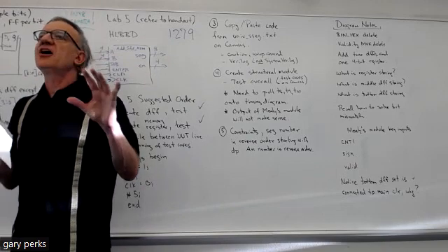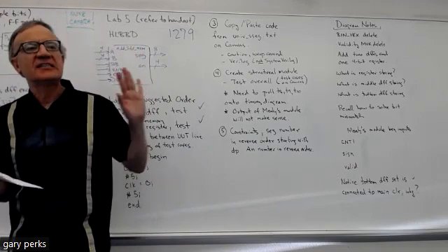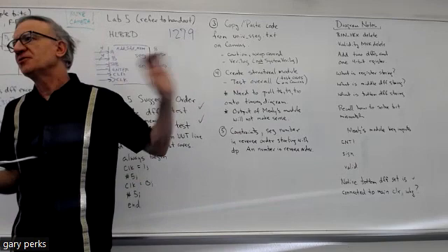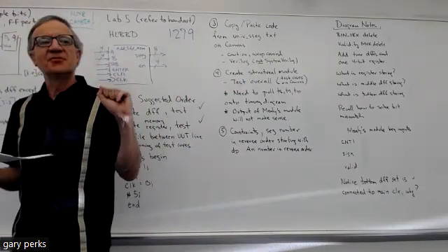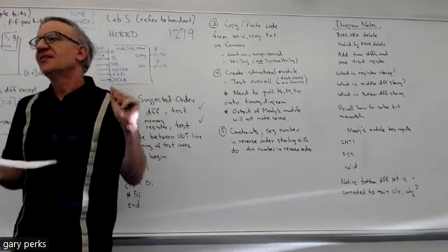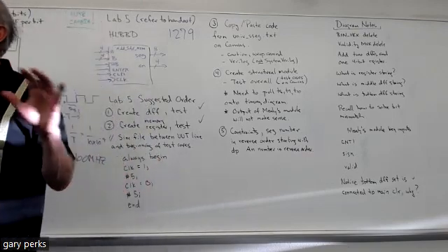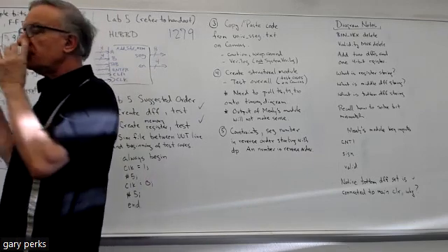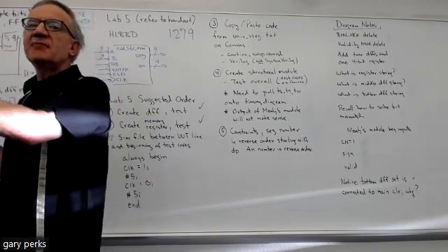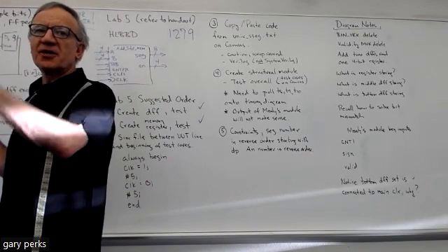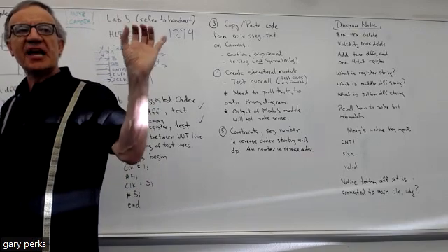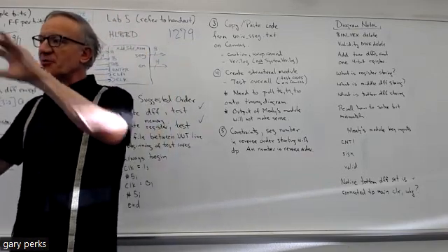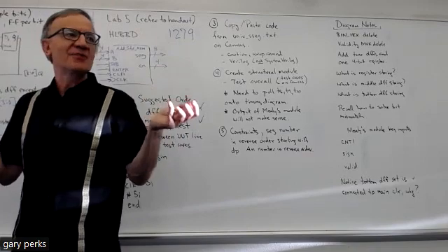But what in Verilog allows you to add bits to the left? You can even do it to the right, but in this case, we want to do it to the left. You remember the term concatenation, right? Remember concatenation is the same as joining bits. So that's what you should do in your code. You may have to look back at that activity that we did several weeks ago, where it had examples of concatenation. That's when you're using the braces, and inside the braces, that's where you put what you want to join. You got to separate it with a comma.